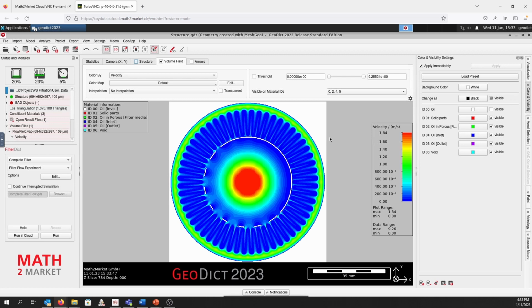This sometimes is quite tedious when, for example, we have very low resolutions and the voxelization is too coarse. So in the end, pleats can be stuck together and no flow can enter, but in our case we see that each of the pleats has flow inside.